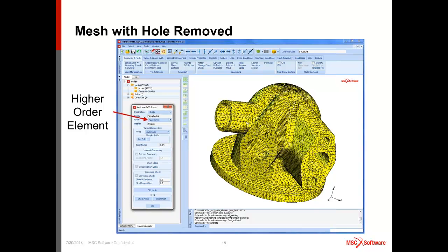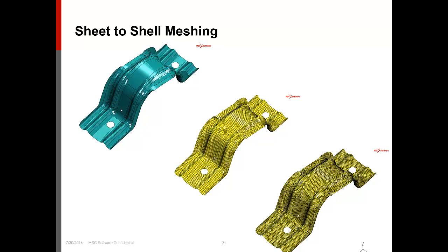So that's a demonstration of the new CAD type technology. In terms of meshing, we can now mesh directly on the parasolid representation of the geometry. So if we had this particular sheet and we said I want a quadrilateral dominated mesh, we can press one button and we get the mesh. If we say we want a triangular based mesh, again, we just say triangular based mesh and we get the mesh. Two things are important.